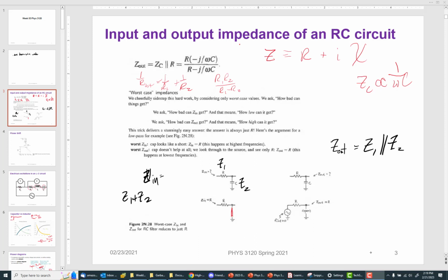Yeah, so to be careful, it's the Thevenin resistance of a two-element voltage divider, right? I mean, if you had more resistors, we've seen in general, it's somewhat more complicated than that for the Thevenin decomposition. But we like to make our lives easier, so we're going to almost always be able to think in terms of a two-element voltage divider.